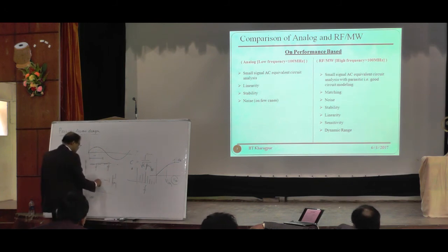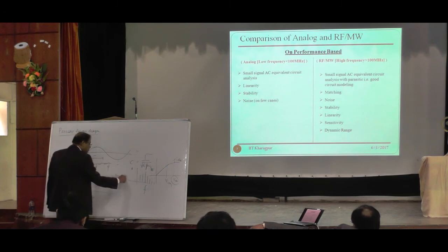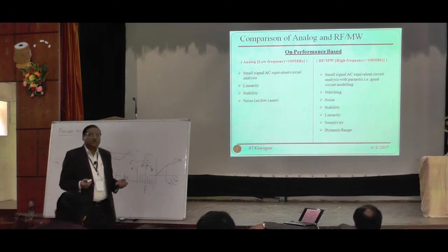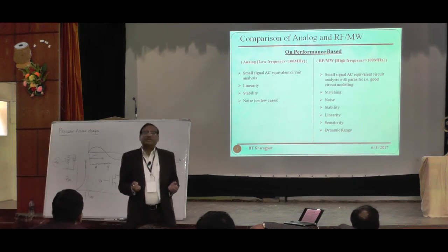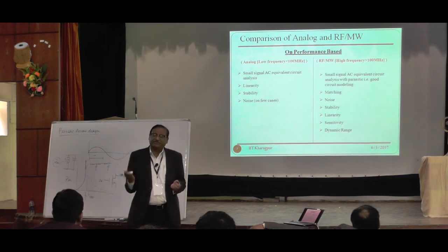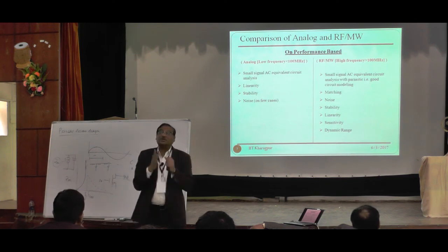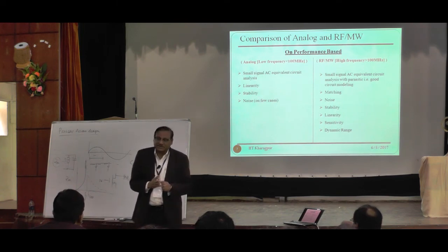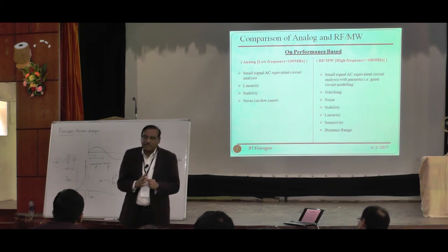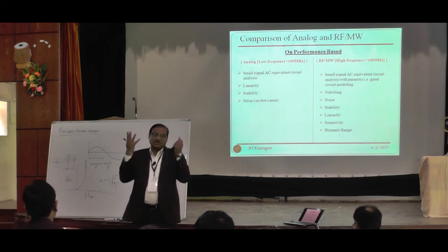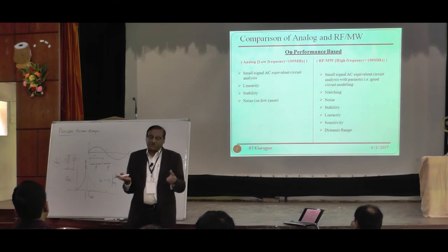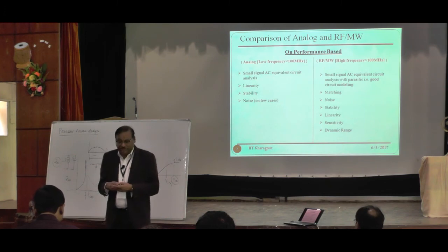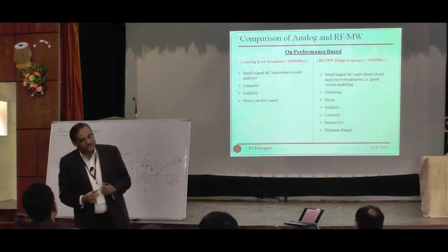So this is my input and I am getting the output. Okay. Now what is an oscillation? Oscillation means a fraction of the output is fed back to the input and added constructively, not destructively. Then at certain conditions called Barkhausen criteria, the system itself starts oscillating without requirement of external signals. I made a story out of that.